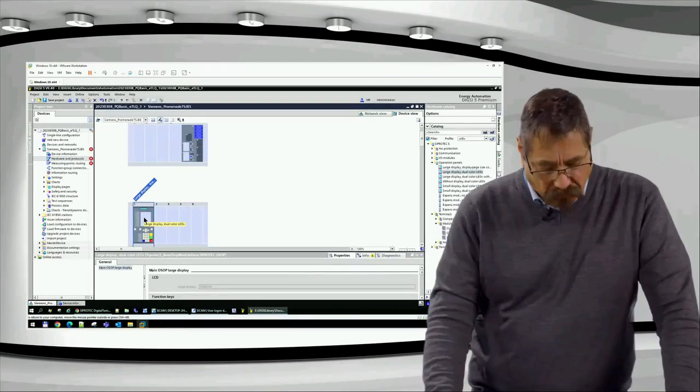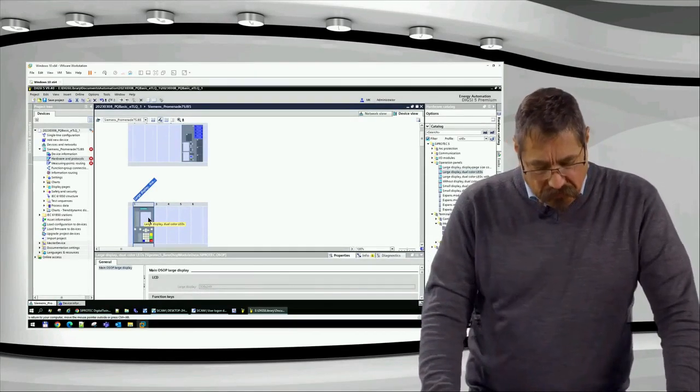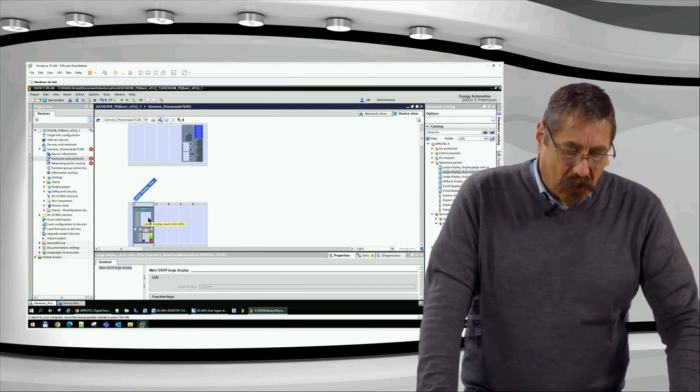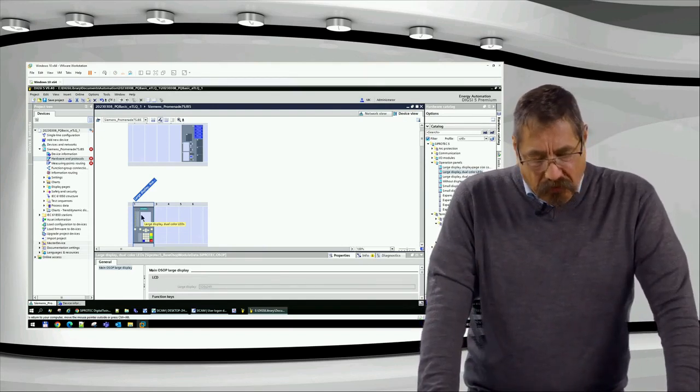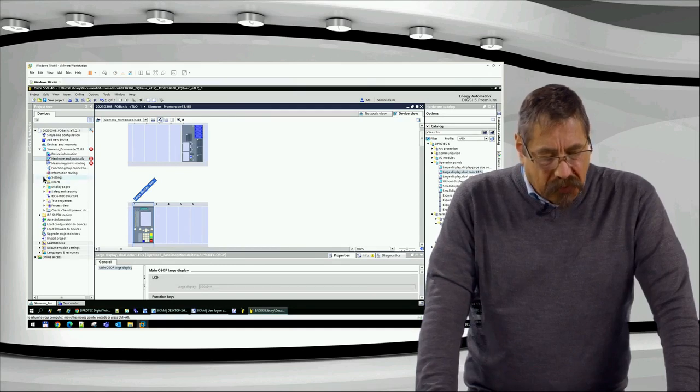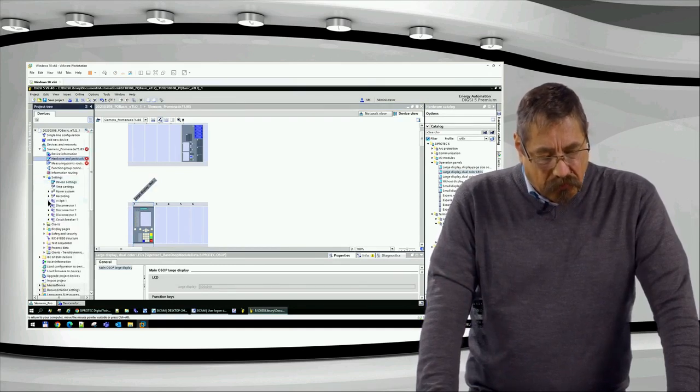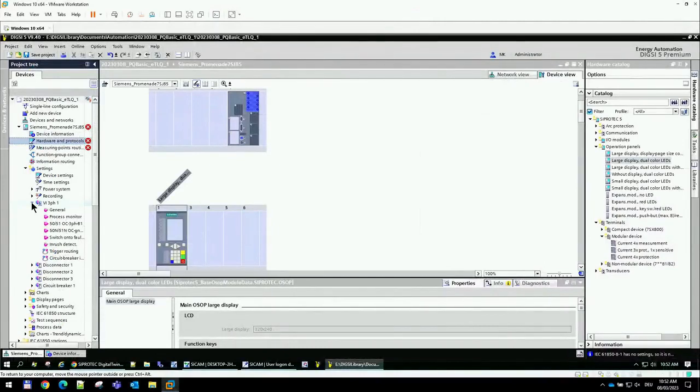Okay, and the next step is essential, what I've already explained is a theoretical part. We have to expand the function group voltage current 3-phase by our power quality function blocks. Here on the left is a function group voltage current 3-phase number 1. And right now only protection, typically function blocks available by default.